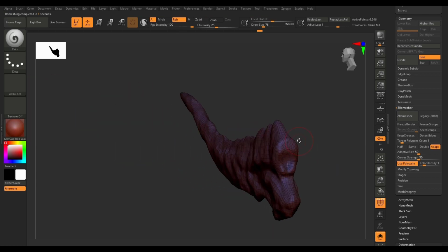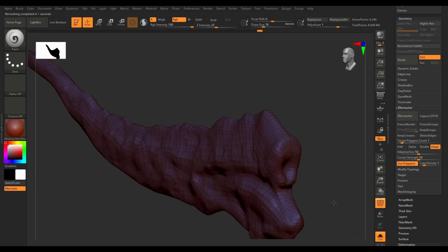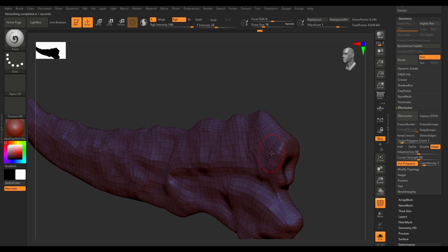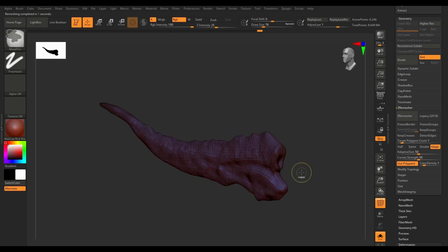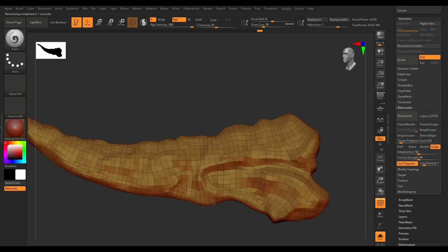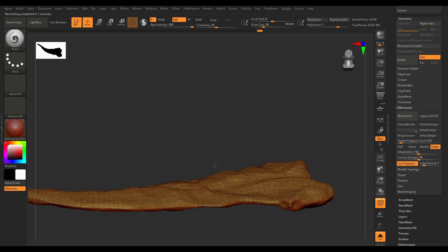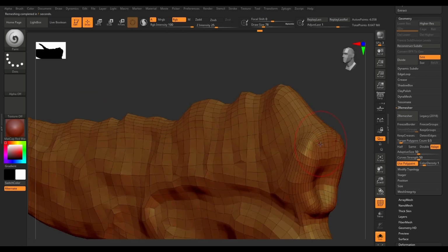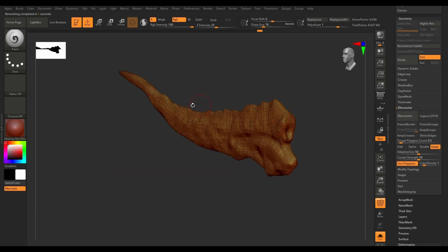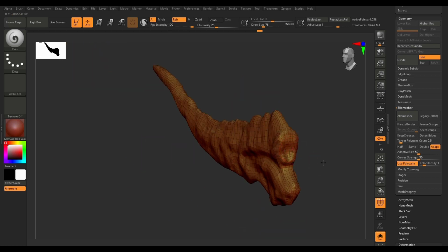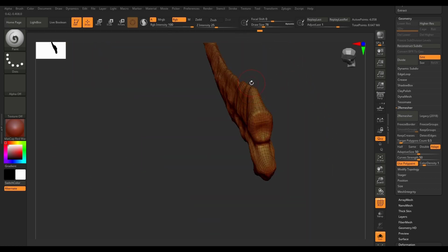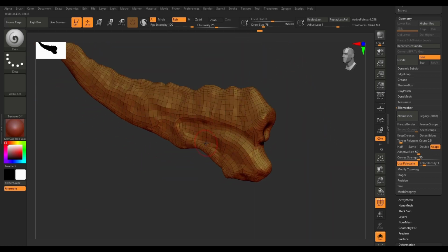Shift F. As you can see, that's good. Yeah, acceptable. You can go a little bit lower. Let's Ctrl Z, maybe 0.5 and remesh. And yeah, that's really better. As you can see, we have more poly at the selected edges and also a symmetrical line at the middle.